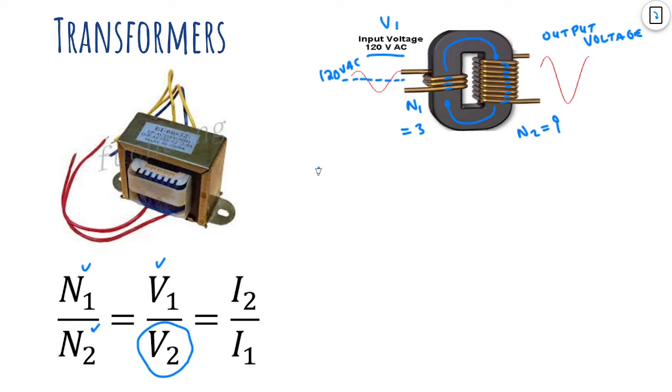And so I take my formula, N1 over N2 equals V1 over V2, and I need to solve that for V2. It's just algebra, but probably the easiest thing is to cross multiply. So I'd end up with N1 V2 when I multiply that way, the bottom times the top on the other side. And then I multiply this way, that equals N2 V1.